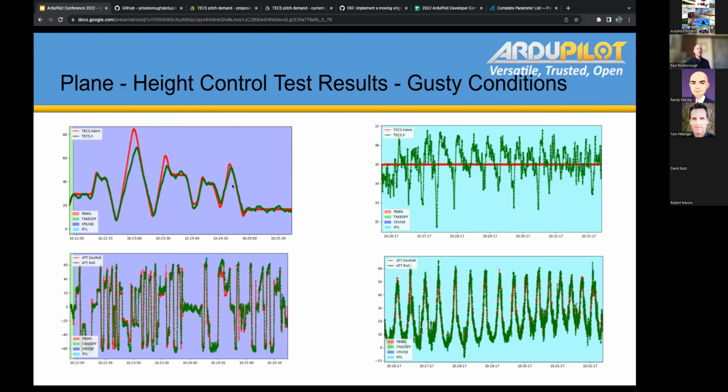And this is the height profile in green compared to the demanded height profile from the user stick inputs, in 9 meters per second gusty wind conditions. That was in cruise mode, and you can see what I was doing with the bank angle, being really vicious to it. I was literally going full reversal one way or the other, doing climbs and pushing the stick forward while doing these large 60-degree bank reversals at the same time. So really very unkind to the poor little plane.